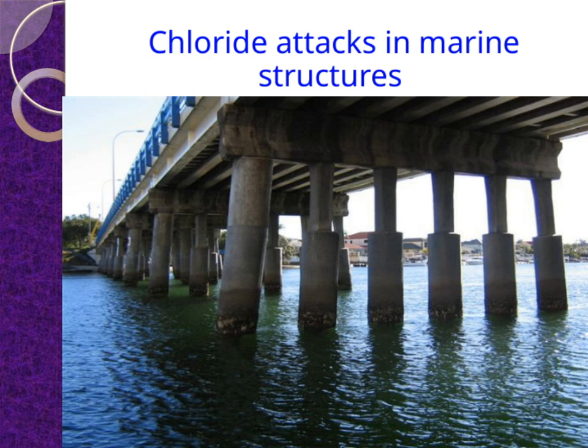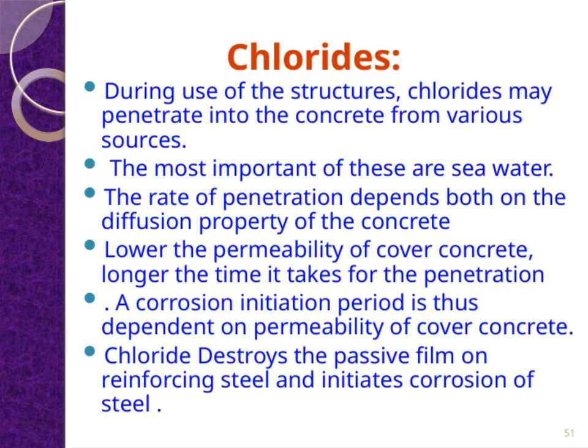It's also important to highlight that environmental factors like temperature, humidity, and tidal cycles influence the rate of chloride ingress and corrosion progression. Connecting this to our overall theme, it underscores the importance of selecting durable materials, applying effective protective coatings, and designing structures with adequate cover and resistance features. By doing so, we can significantly mitigate the detrimental effects of chloride attacks and extend the service life of marine structures.